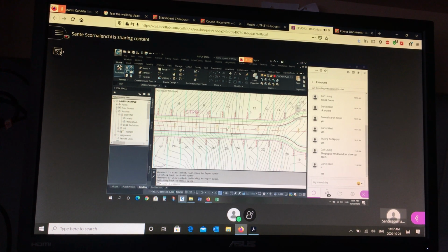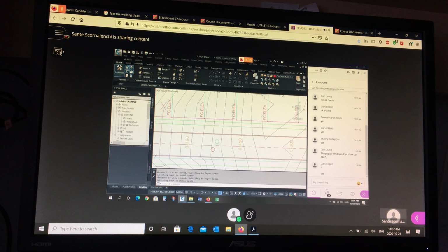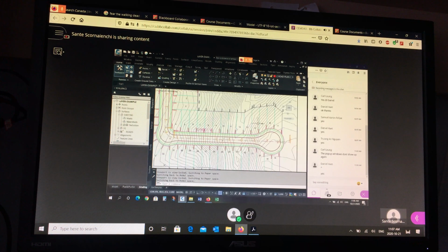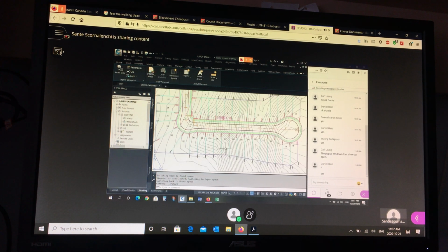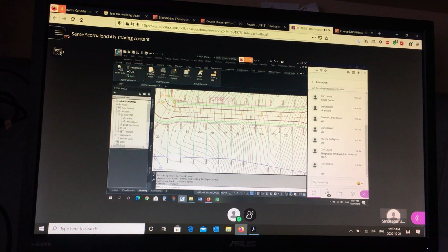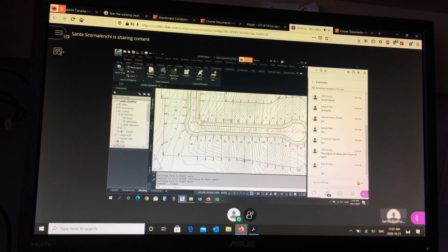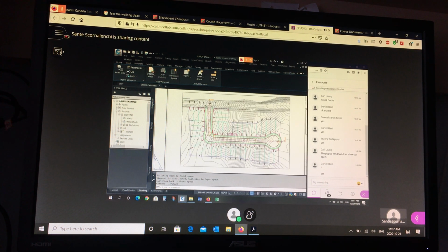Okay. And then I don't want to see the water meter, so I'm going to freeze the water meter. Anything underground should not be visible here. Only the surface information. And that's a grading plan. It would include labels for the contours and so on. Okay. And it's not complete yet. We're just getting ready. We're going to add a whole bunch of points between the front and the back. That's assignment 4. We'll get to that after the break, right? We're certainly going to start that discussion today.